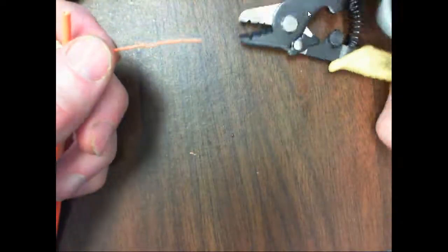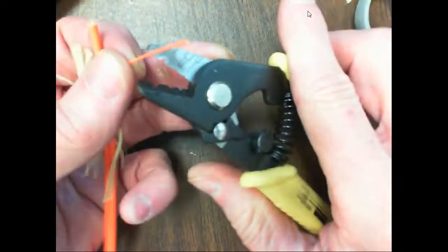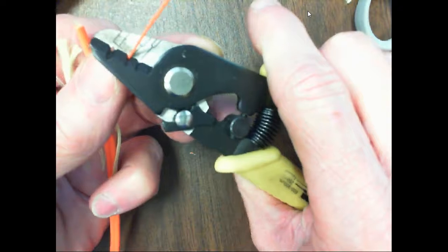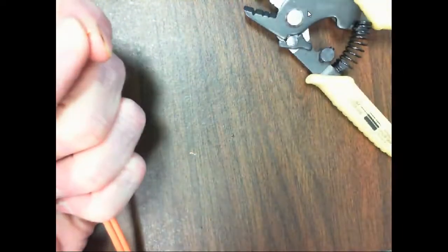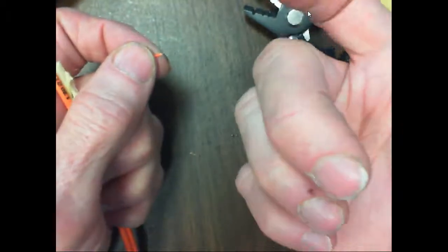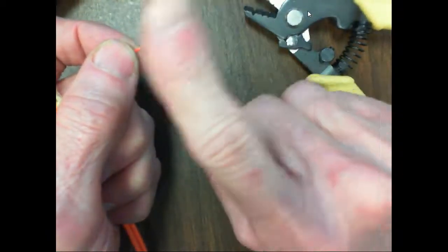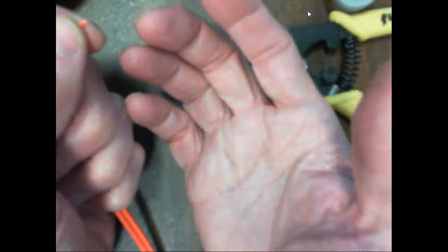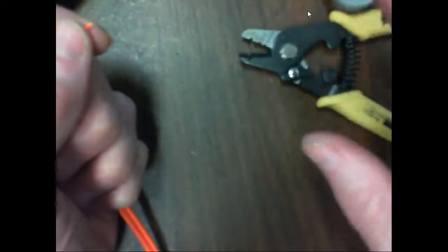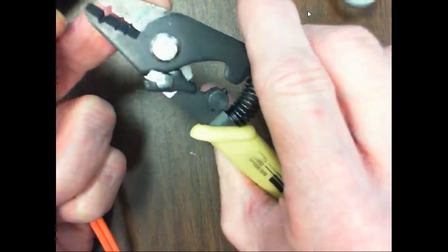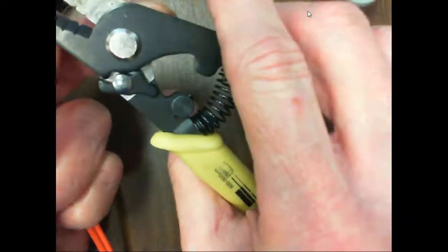This is a tight buffer. Okay. So I'm going to drop down to my next notch to cut off the buffer. And usually we don't do that much because you want to do it in about a 1/4 inch, because it's glass, guys. What we're looking at here, this is the coating. And the buffer coating is strictly in there to protect the fiber. That's all it's in there for. It has nothing to do with reflecting light. But if we're going to terminate it, we've got to get that buffer coating off there.